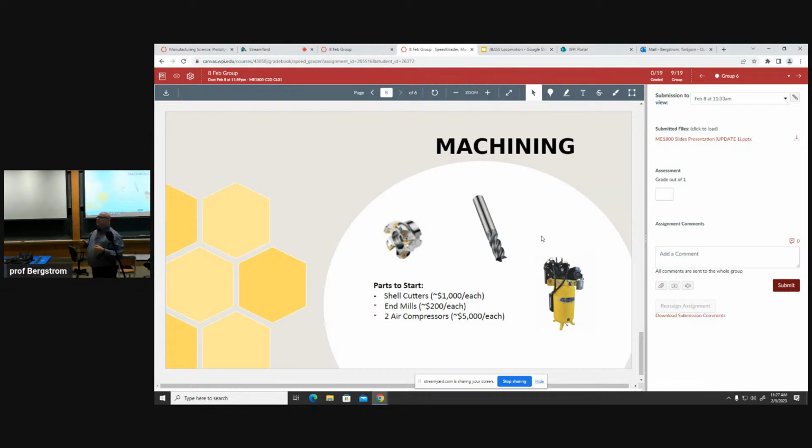So we moved a machine shop back in 2016 and there were 15 different machines, different levels of sophistication. Some of them were small little hand tools that plug into the wall. Some of them were big lathes that need 480 volts, 3-phase power. Moving the machines from one building to another cost about $6,000. The move of the 15 machine tools happened in a day, the day after Christmas, December 26th, in an ice storm. So the move part wasn't so bad. It cost $27,000 to hook up the power.